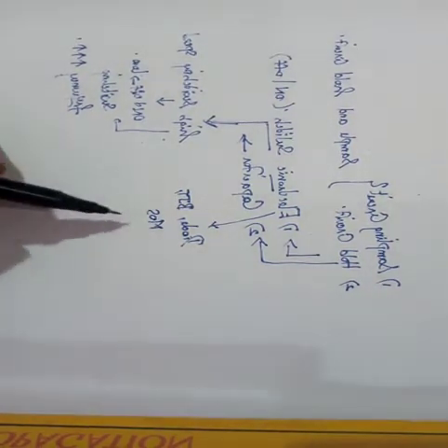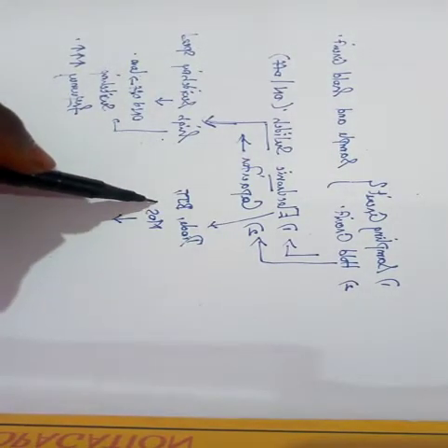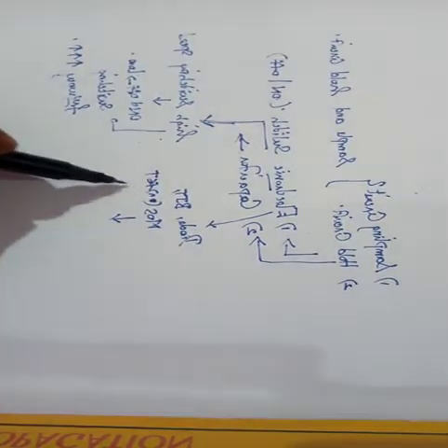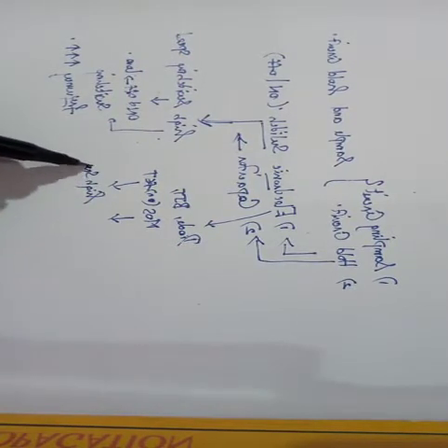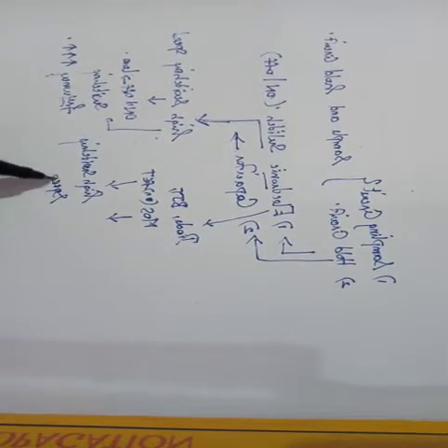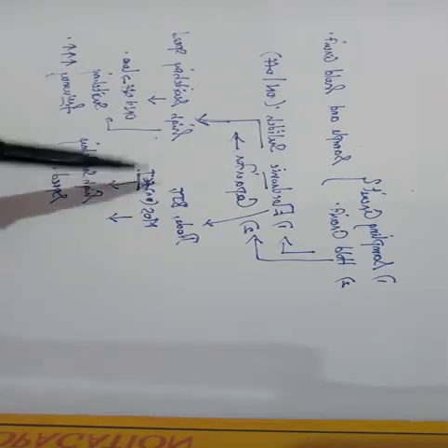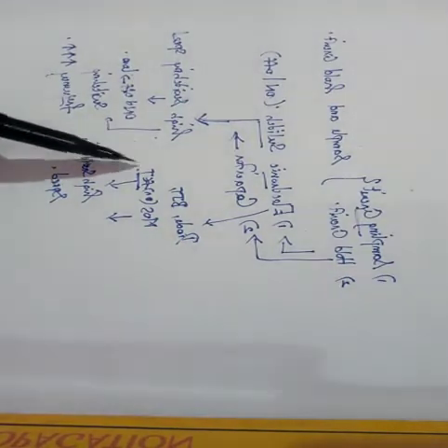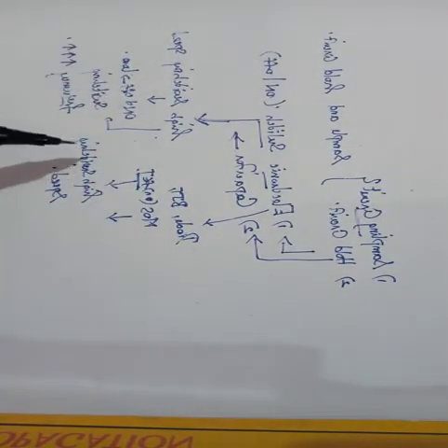As we already know, MOS or FET switches will have a very high switching speed, so preferably you can go for a FET switch to accomplish the sampling operation, as the FET switch will have a very low on-off time.